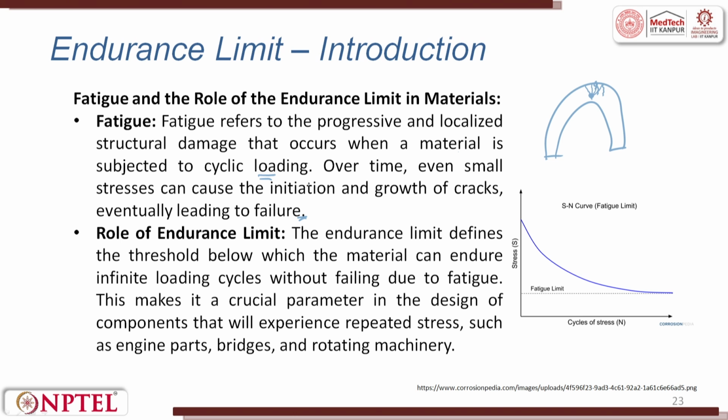Over time, even a smaller stress can cause the initiation to grow as a larger crack and then lead to failure. So, the role of endurance limit is always very, very important. The endurance limit defines the threshold below which the material can endure infinite loading cycles. So, when you try to put this, this is the fatigue limit. This is the fatigue limit.